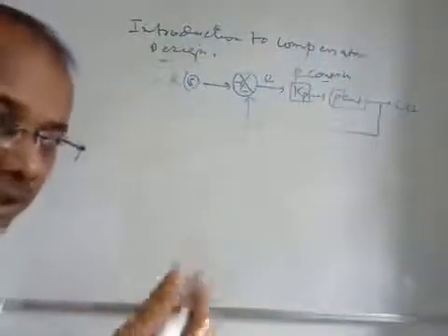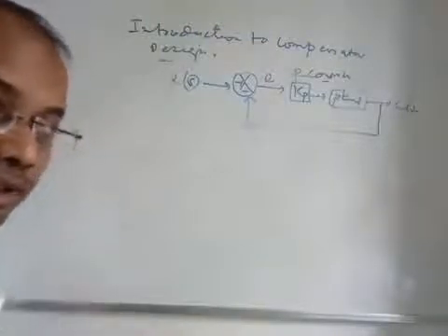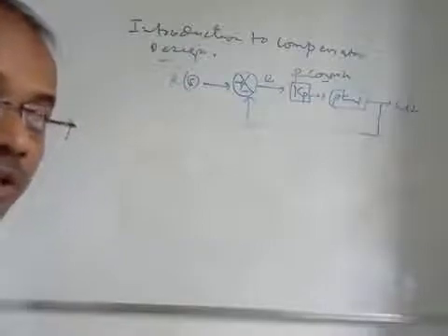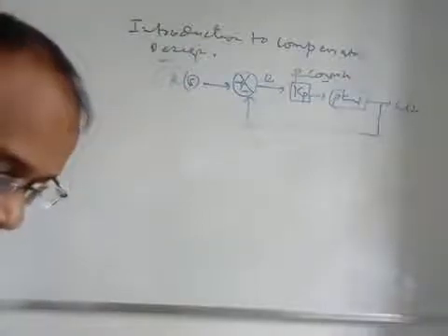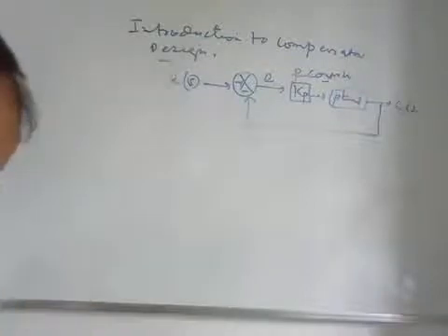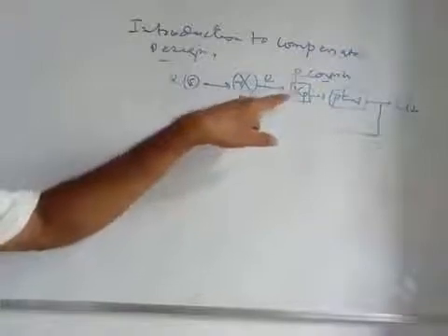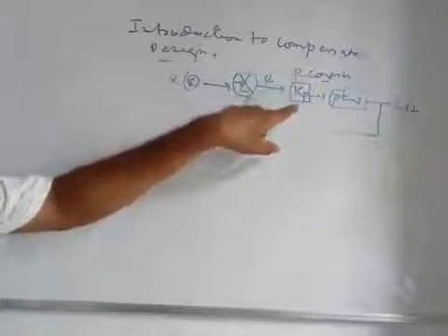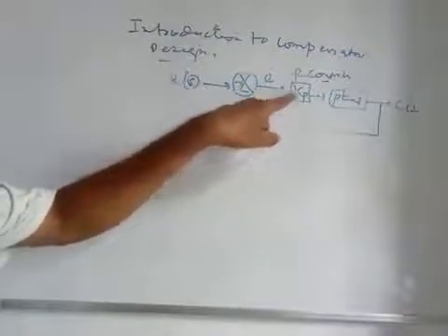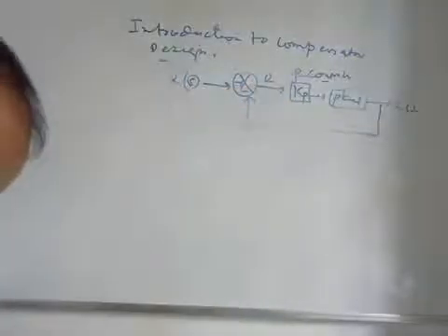Once you vary the gain, from the root locus or from the time response, you see what happens with the variation of the gain. You get the system either stable or maybe unstable. So in the case of a proportional controller, you can add an integral controller, a derivative controller, a PD controller, a PID controller, or a PI type of controller.